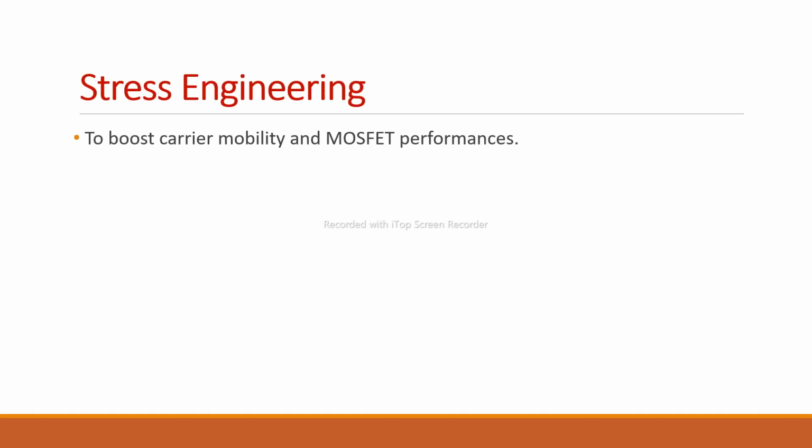The first technology used for MOSFET scaling is stress engineering. But first of all, why is this technique introduced and why is it required? The reason is that the shrinking of device size is essential but not sufficient, because simple scaling is reaching the limit in terms of scaling and CMOS performance improvement. So this stress engineering technique is used to boost the carrier mobility and the MOSFET performance.